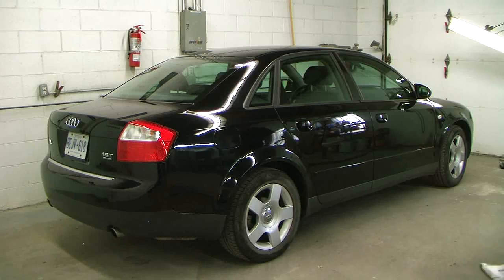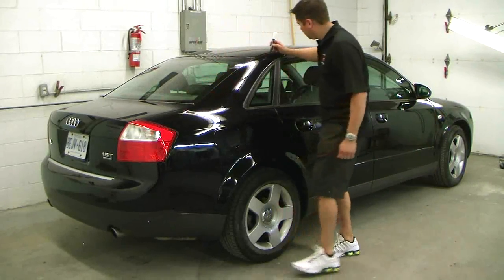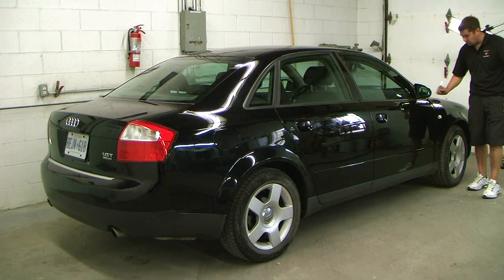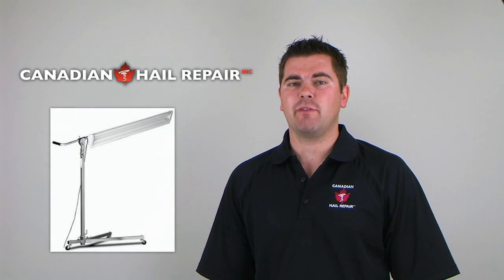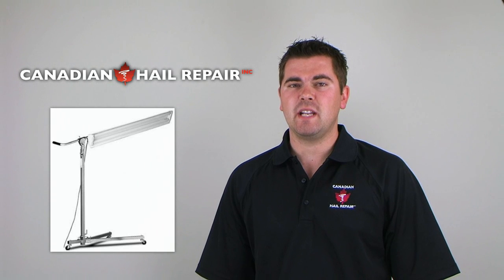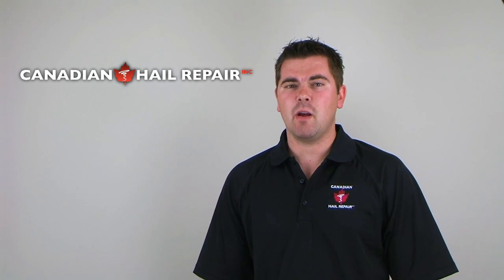First, it is important to check all panels of the vehicle with a magnet to identify whether the panel is steel or aluminum. The hail light we're using is a fluorescent style tube with a special shading on it to cast a soft reflective shadow on the vehicle, highlighting all the highs and lows of the dented panel. It is important to note you cannot generate a proper hail estimate without this type of light.